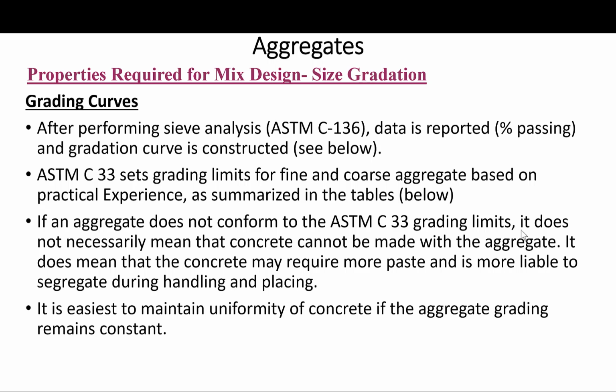We also talked about the size gradation, basically size grading. We talked about size analysis. We talked about the maximum aggregate size and its effect on the voids, which is basically the paste requirement, and its impact on the strength as well. Today we will continue our discussion on the grading curves.